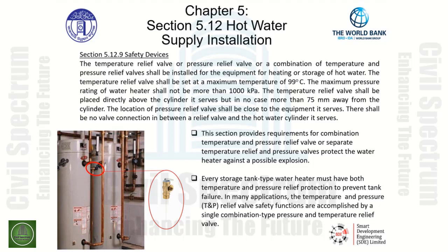Every storage tank type water heater must have both temperature and pressure relief protection to prevent tank failure. In many applications, the temperature and pressure, we say T and P, relief valve safety functions are accomplished by a single combination pressure and temperature relief valve.